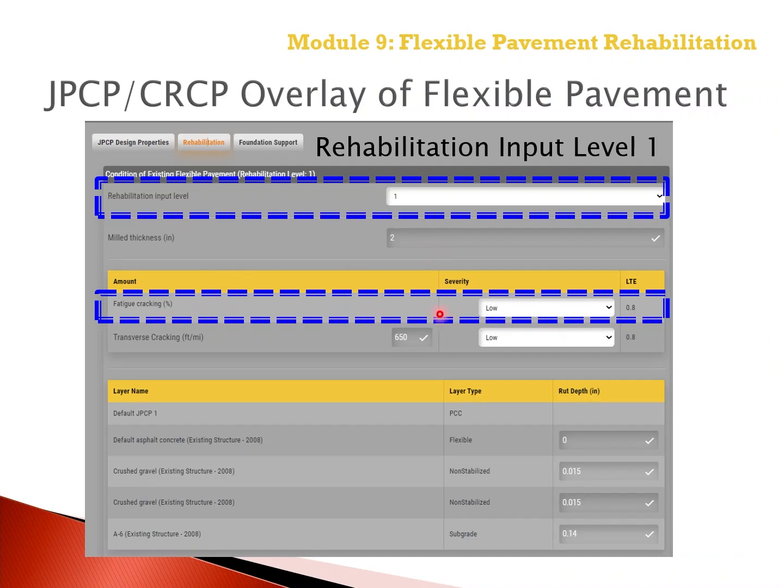So the fatigue cracking basically is defined through the back calculated layer moduli, the damaged modulus versus the undamaged modulus, as we previously discussed. It's entered in exactly the same way as when we had the software open, and as we discussed for structural asphalt overlays of asphalt pavements.